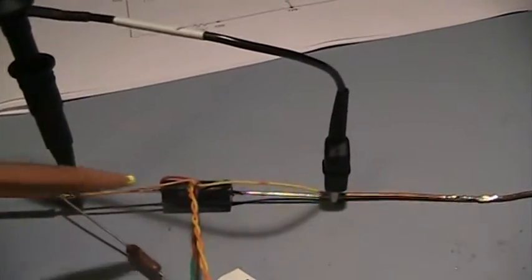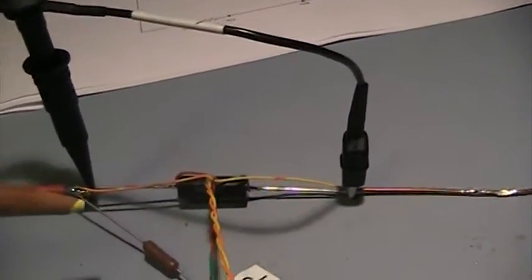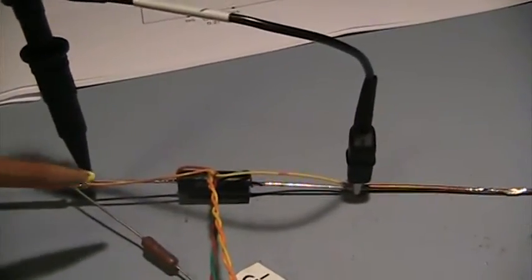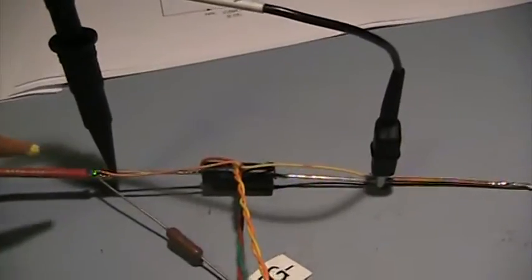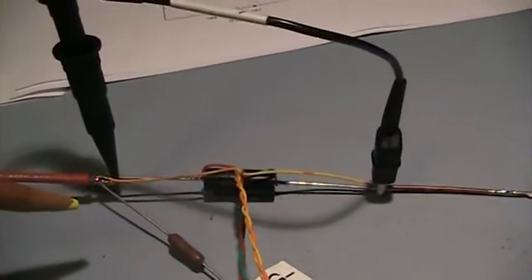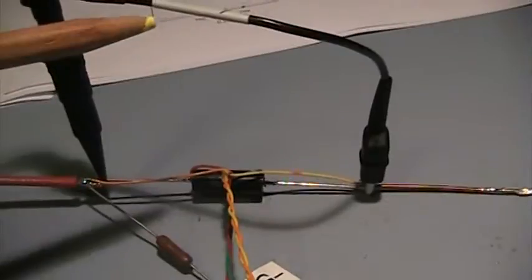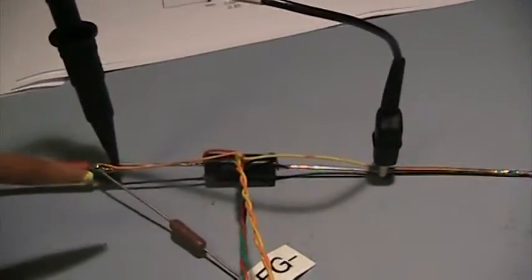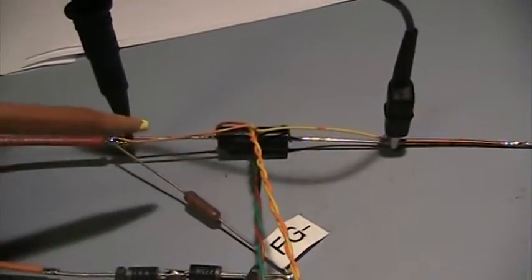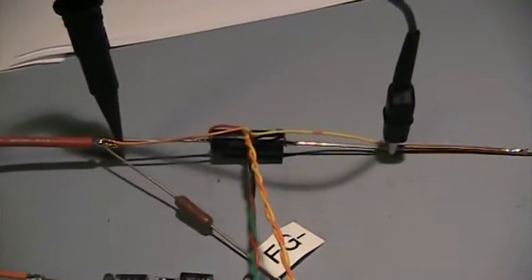So that's going to give us an indication on the scope, and that's going to be used as part of the multiplication process with the battery voltage to give us our instantaneous power product. And that, of course, is going to be an erroneous measurement, because we are picking that up via induction. It's not a real current flowing through the circuit here. It's being picked up via induction.